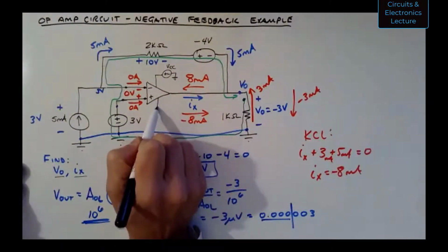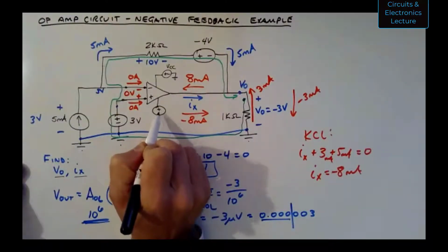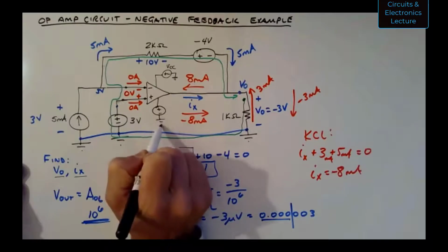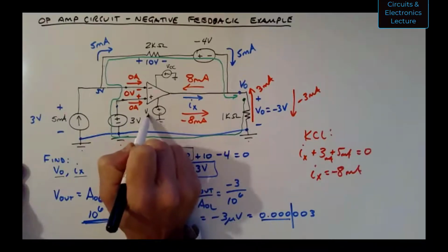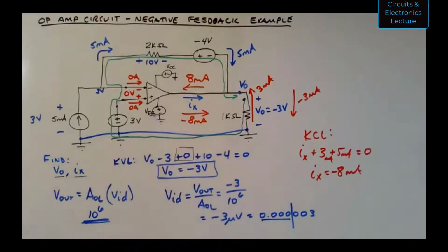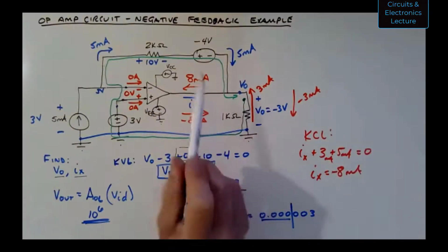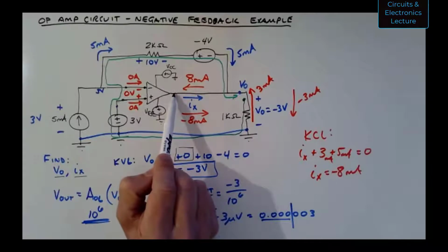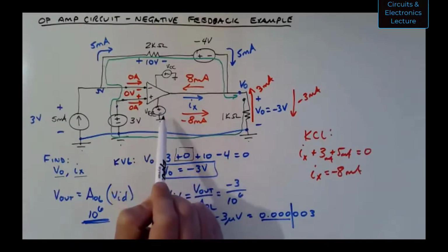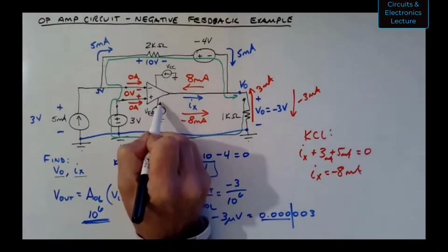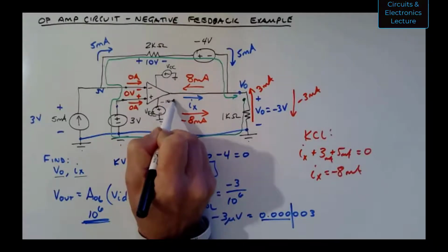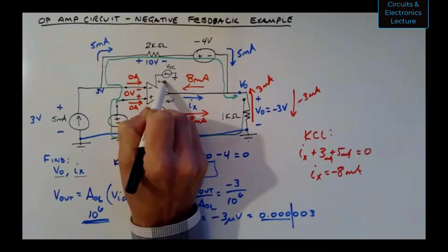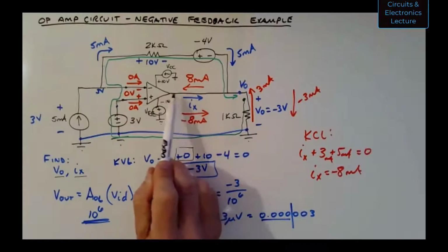And I'm going to put another voltage source here, plus, minus, again to ground. So this is VEE. That could be something like minus 10 volts. So this current coming into the op-amp, in this case, is going down to VEE, right? So this is a negative voltage, something like negative 10 volts, and this might be positive 10 volts here. And that's where that current is going.